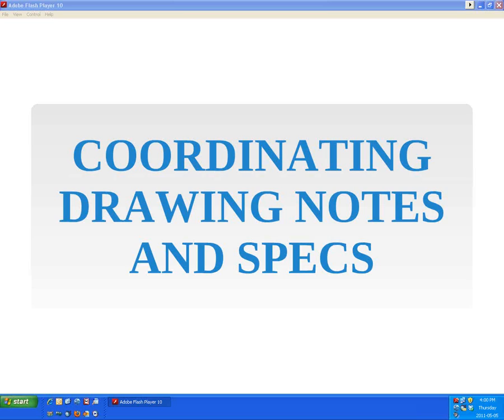And that's exactly what we were talking about earlier about being too specific in the notes. It's just not necessary. If you're on an architectural sheet, you just point to it and say it's structural steel, and then the contractor knows that that's not miscellaneous steel in section 5005-5000, but it's part of the structural stuff, and to look on the structural drawings. You don't even have to say see structural drawings, just call it out as structural steel.